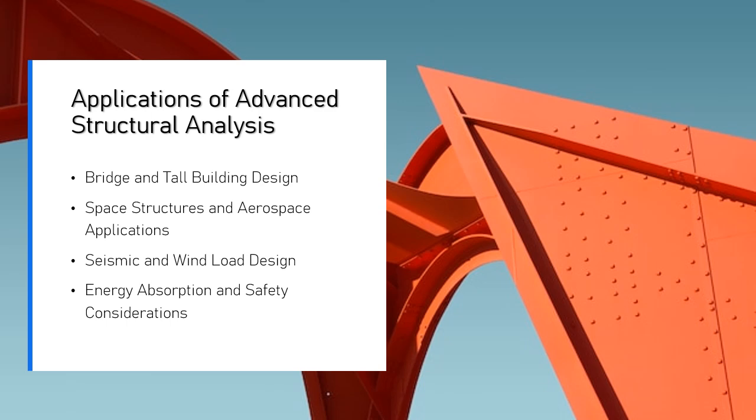Modal analysis is often employed to ensure the building's fundamental frequency does not match the wind's frequency, which could cause resonance and significant structural damage. Outcome: tuned mass dampers, which are designed to reduce the amplitude of structural vibrations, are often incorporated into skyscrapers to counteract the effects of wind-induced motion. Advanced modeling ensures that the Burj Khalifa and similar structures are capable of handling wind forces safely and effectively.